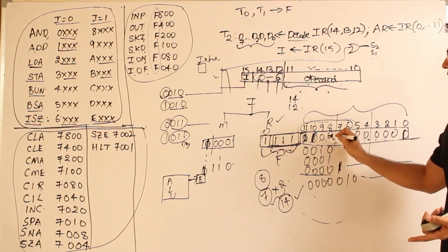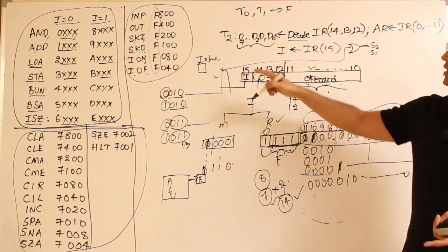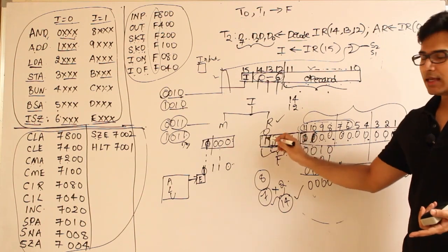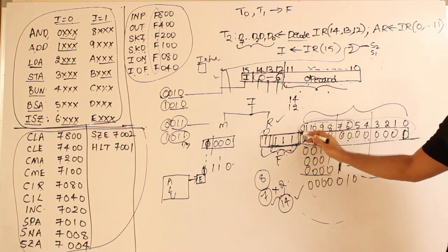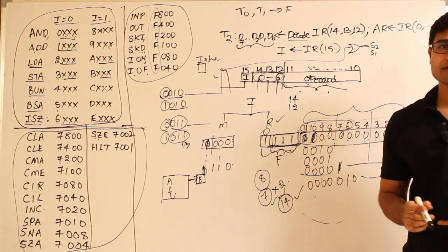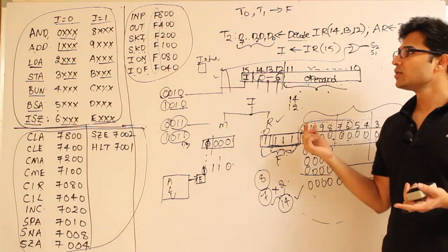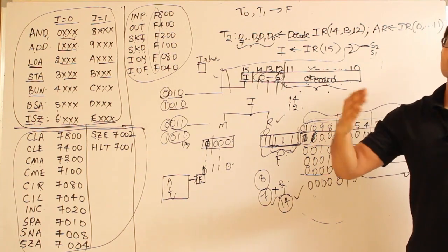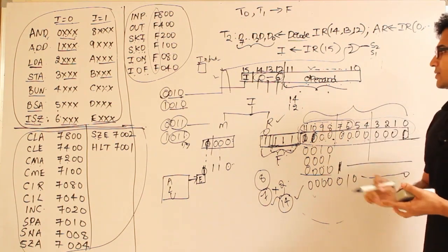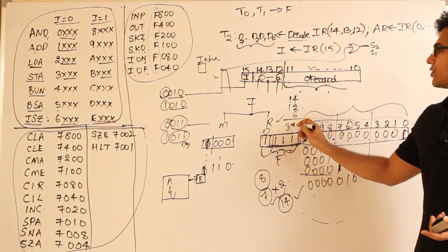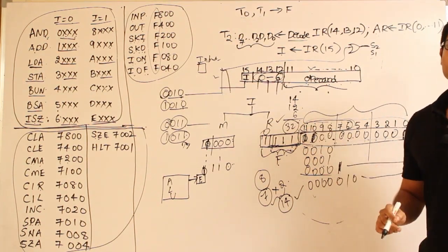Got it? And then after that for the IO, again we have fixed all the bits to be ones, and using these 12 bits we could have framed 12 different IO instructions, but since we don't need that many, we want to keep it simple, we have used only 6 of it. In fact we could have extended to 12, but we have used only 6. Therefore we have gone for 6. So I think how many? 32 instructions are totally implemented, isn't it?